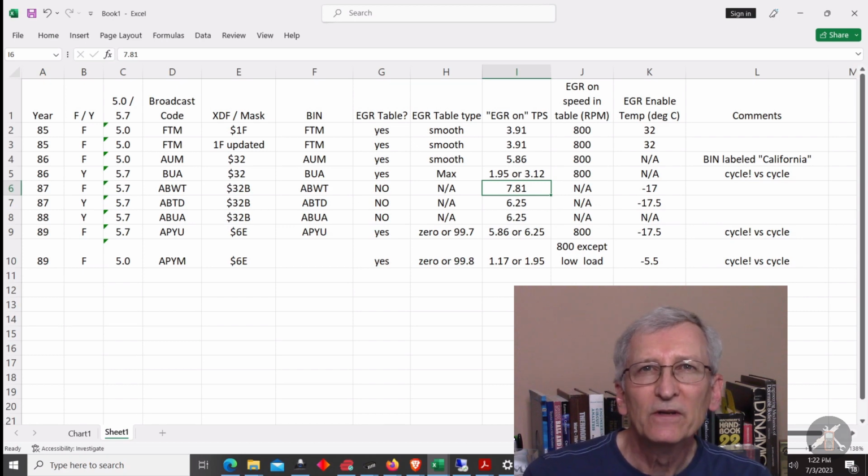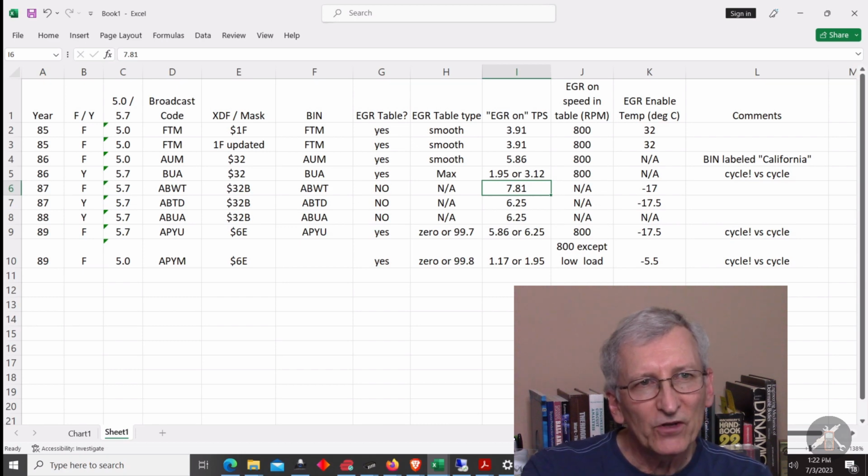Or could you skew it a little bit so that it reads higher? I know typically TPS is supposed to re-zero itself to a point. It's supposed to look at your zero value and adjust for a zero voltage, but I hate to suggest making adjustments, but I would be tempted to look at that.